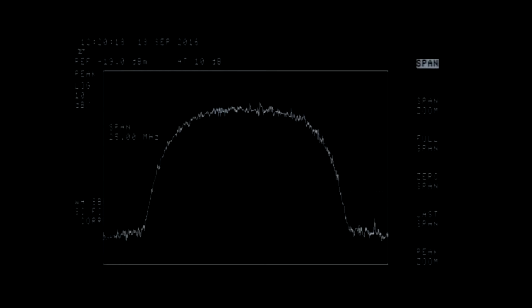As you'll notice, the spectrum is losing some of its shape, and that's due to the hardware filters on the DATV Express board. They're actually plus minus 5 meg filters, roll-off 3 dB points I should say. But you can demodulate this signal with a SatLink receiver. But that's about it. It won't go any further. The Express FPGA can, but it's limited by the filters on the hardware.